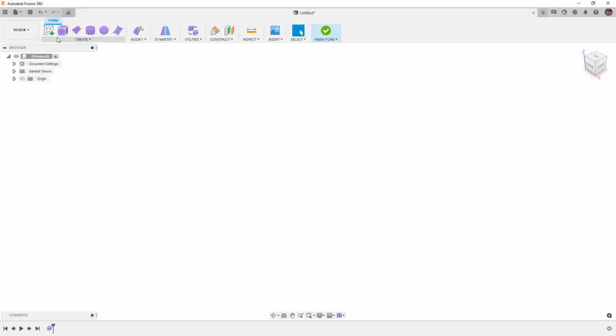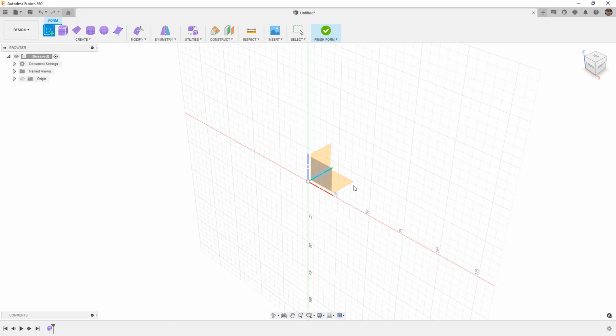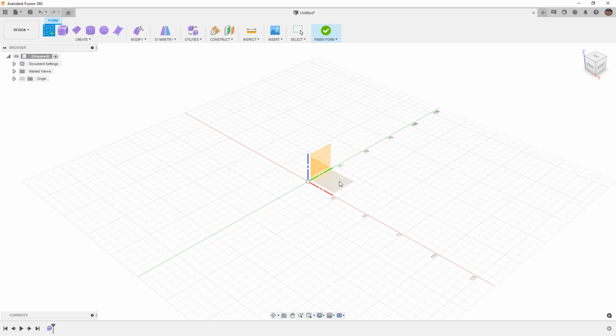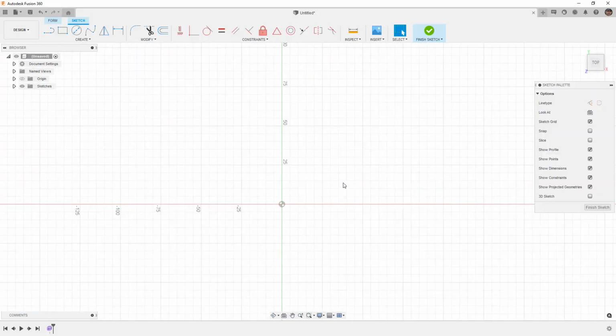So the first thing that I want to do is start with a sketch. In this case, I want the rim to be visible from the right plane, which means I'm going to sketch this on the top plane. We're going to begin with a line. I'm going to start at the origin, go out to the right, hit OK. I'm going to come up vertically, hit OK, and then I'm going to draw a horizontal line and hit Escape. We want to use a midpoint constraint between this line and here. And then we'll hit Escape, select these two reference lines, and make them construction.